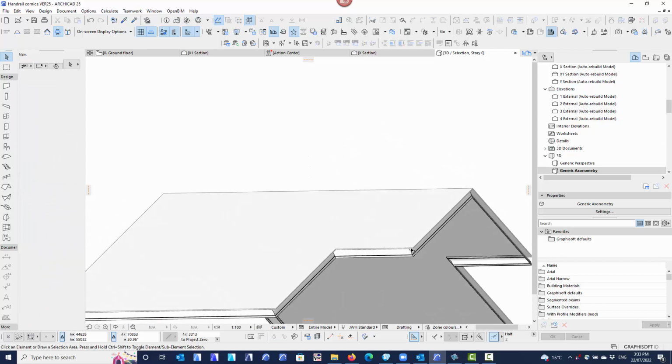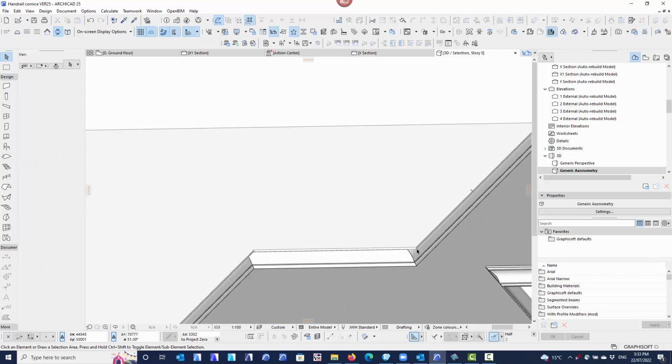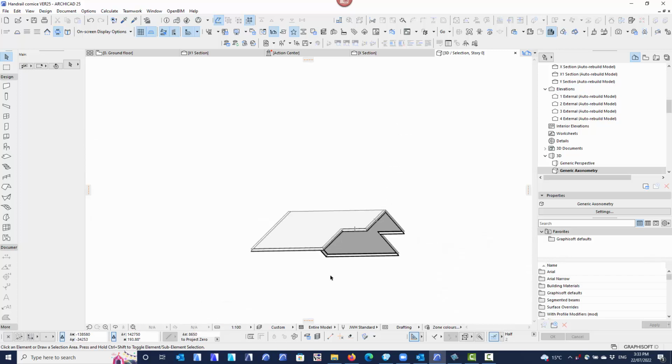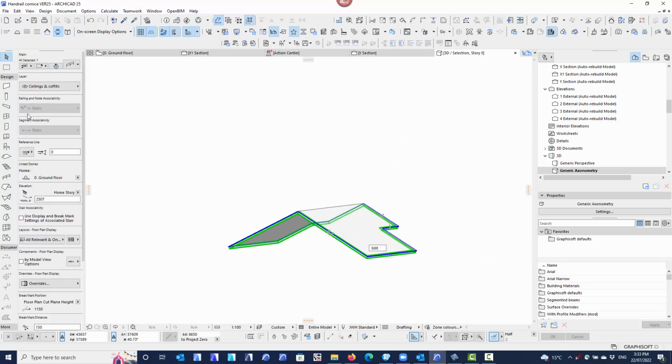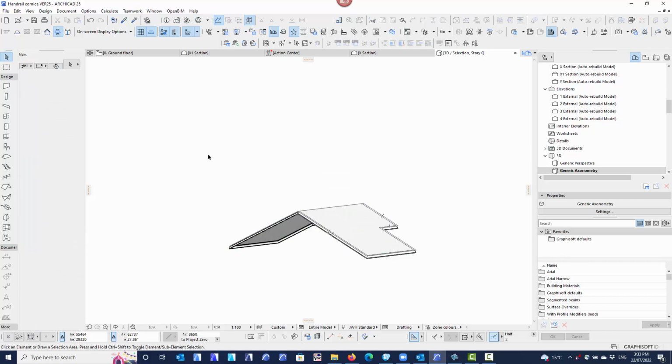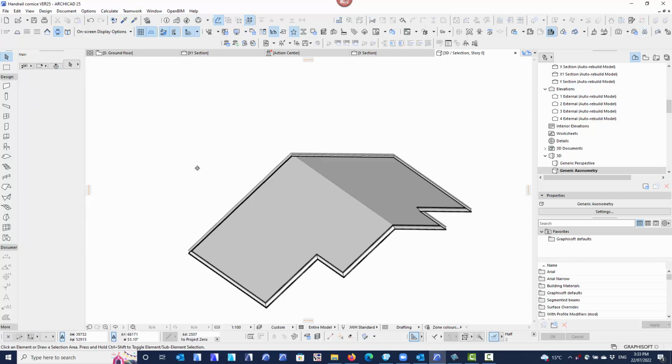Same when you're doing this. If you were to drag it from this node down to that node, it won't work. You have to drag it from this node vertical to this node here for it to unassociate. You can select these at any time and you can tell it to unassociate, but it will just reassociate again. So a little bit annoying. There's your railing cornice.